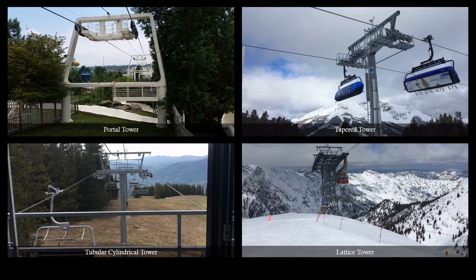On the top right, we have a tapered tower, where the radius of the tower increases as you get closer to the ground. This helps offset the increased bending moments that are created towards the bottom of the tower. On the bottom right, we have a lattice tower, in which a steel framework is used to create the tower shape instead of a tubular or tapered piece of steel. This is used for towers that have much higher loads and are commonly found on larger ropeway systems such as aerial tramways or tri-cable ropeways.